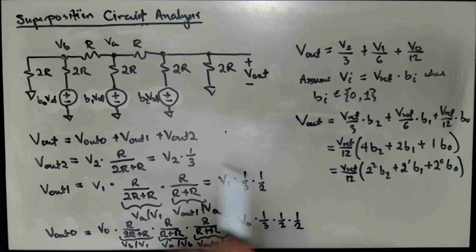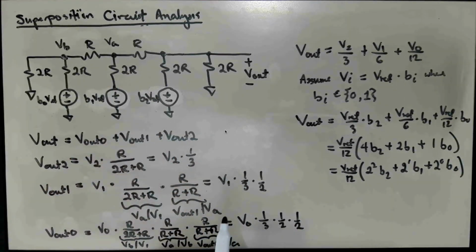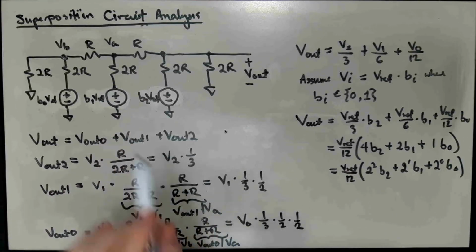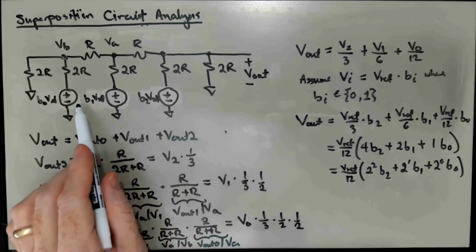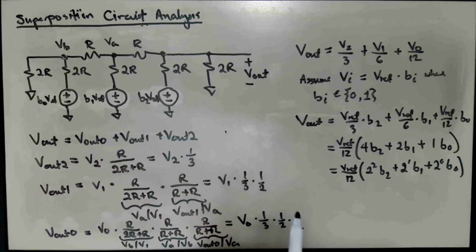And this R-2R ladder network is giving us the proper weighting of the input voltages, which are either low or high, and it's also providing, via superposition, the summation. So this is actually a really, really cool resistive network. This R-2R ladder network, in several of its different uses, is probably my favorite resistive circuit.